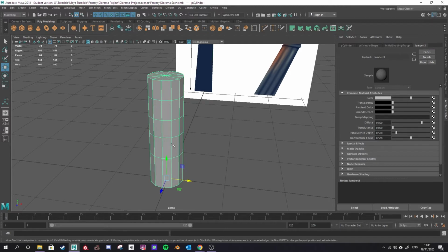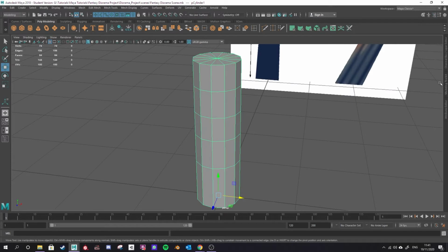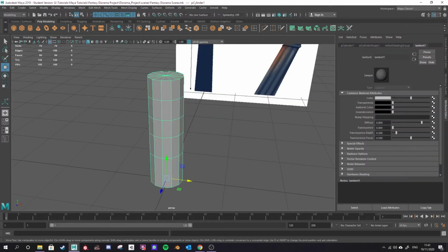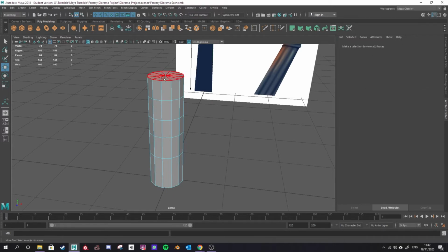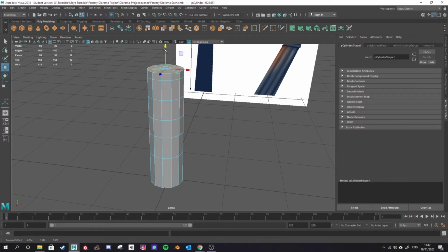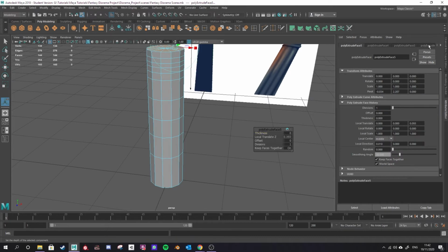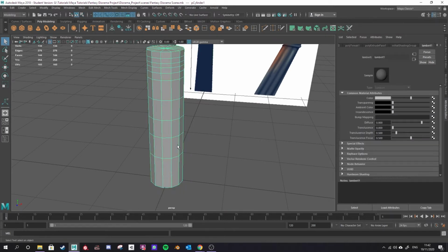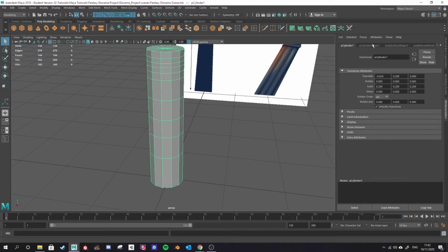So whenever you add a texture to your objects, that is where they'll be, in the attribute editor, and then as far right as you can go in this options window. Now you'll see that my history gets recorded if I say select these faces again and begin extruding. Okay, the history of all of that adds into my attribute editor now. So what I'll have to do if I want to select that object's material is I'll likely be way across here at pCylinder1 or pCylinder shape1.